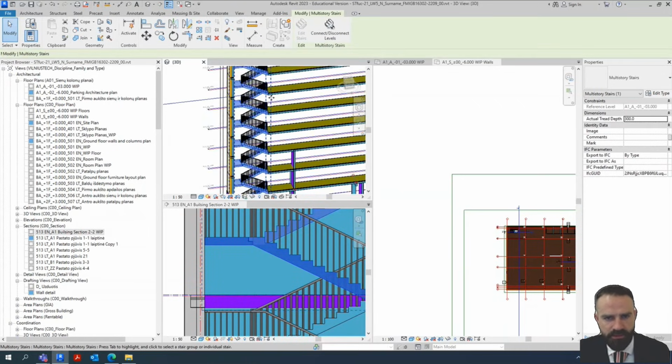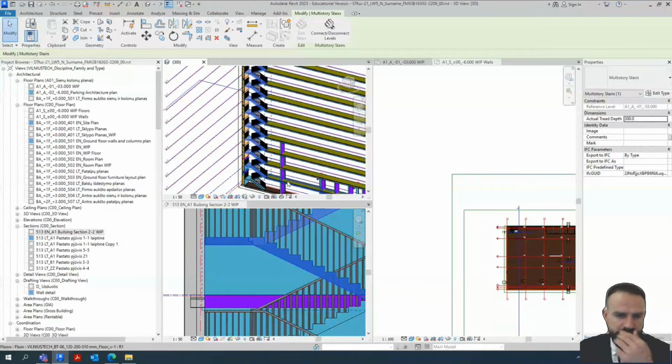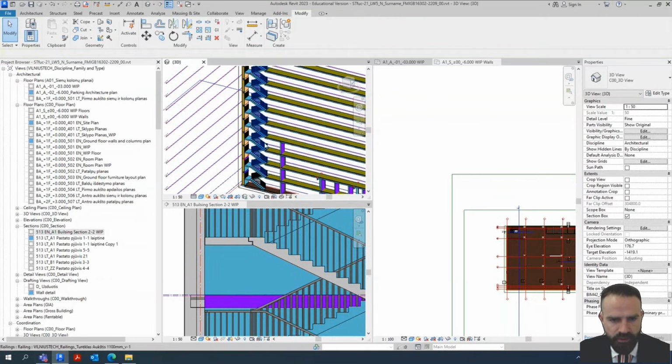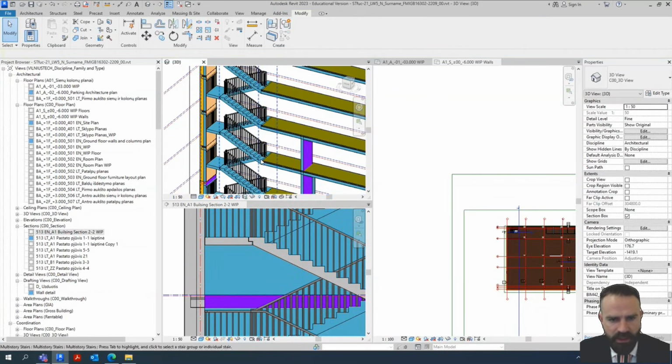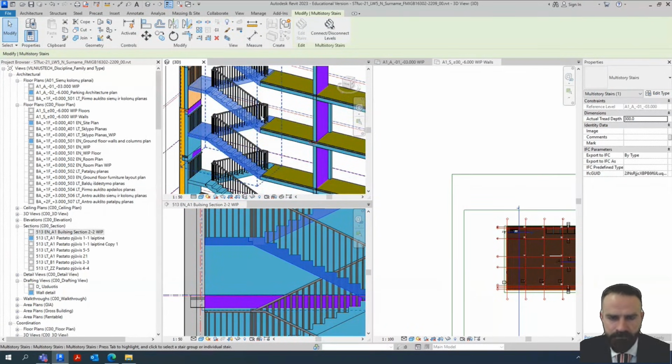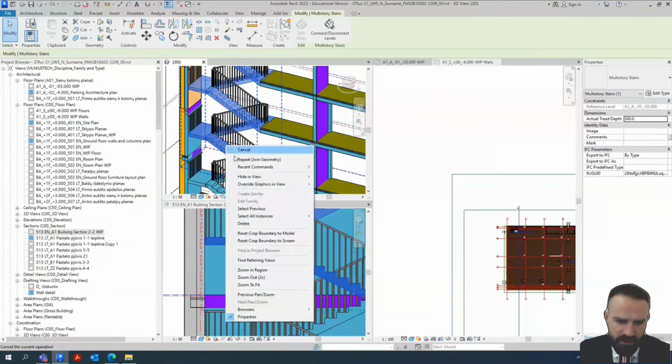The problem of this tool is if I connect all the stairs using this tool, I cannot disassemble this group like a typical group, because it's a specific group for these stairs. And if you made a mistake on the stairs below, fixing it, yeah, you can double tap, I think. No, double tap doesn't work.